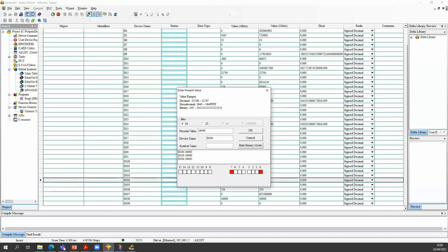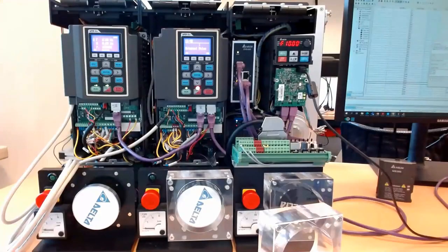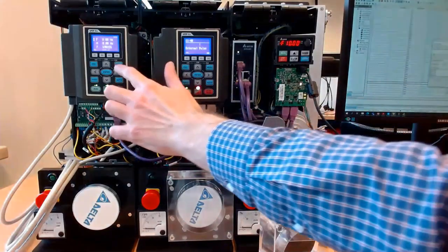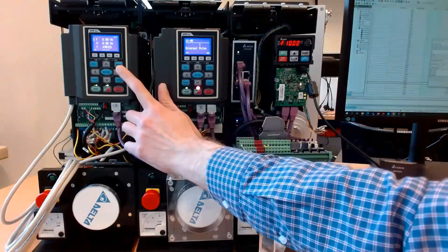And you can also see that when I share my screen here. So I set bit 0 to off, and now I set it on again, and there you have it. This is currently set for relative positioning. I can also set it to do absolute positioning, but for that, first we need to do a homing. So in order to do a homing, firstly, I need to disable this.